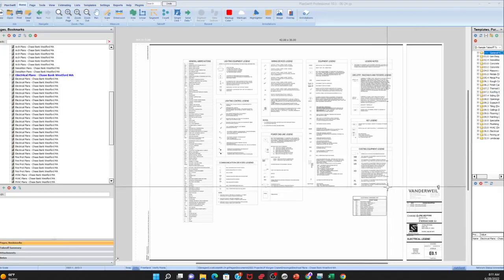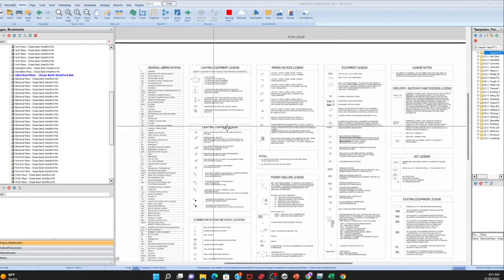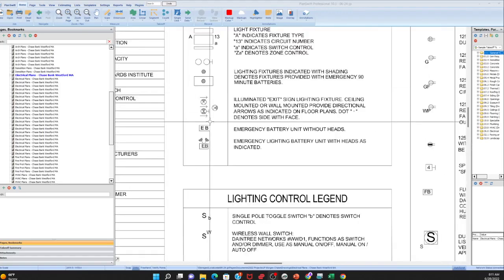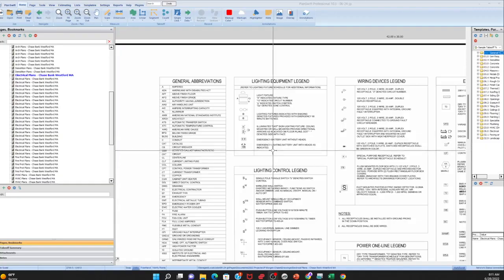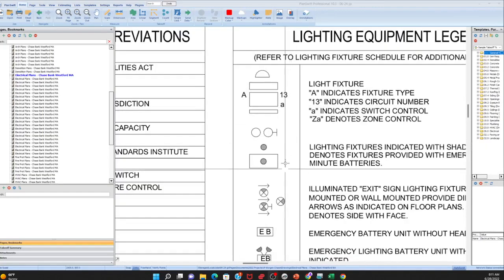All right. So now what we're looking at, of course, is the cover sheet. When you're doing your electrical, it really depends on the architect and the engineers on the symbols. You'll get a symbol in one set that you'll know what it means: okay, that's a duplex outlet, that's a single pole switch or whatever. But then you'll get another set of plans, and because of the style of the electrician, the electrical engineer, the architect, it'll be the same symbol, but it'll mean something different. So just make sure you always review all of your symbols ahead of time.